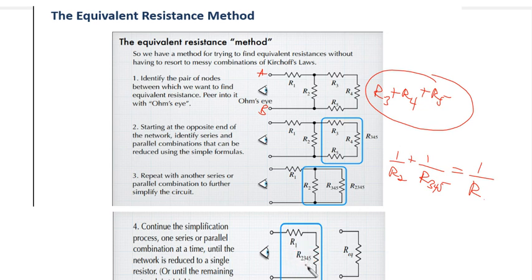This is simply saying that this total resistance is a consequence at this level, because we are still having R1 there. At this level, the total resistance so far is a consequence of all these resistors: R2, R3, R4, and R5. We started by identifying the ones in series and dealing with them, and then going to the next phase, we have parallel, and we deal with them. So far, we have resolved 2, 3, 4, 5, and we have this value.